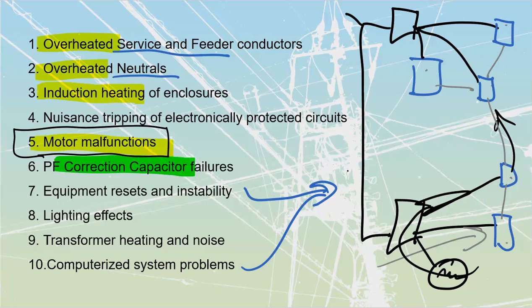Anytime that you get changing of your frequency caused by harmonics that are going to be overlaid on top of it, you're going to lose that timing. And then as soon as you lose that timing, all sorts of stuff starts to happen. Usually your computer systems are going to be robust enough that they're going to be able to sense that they've got poor timing.